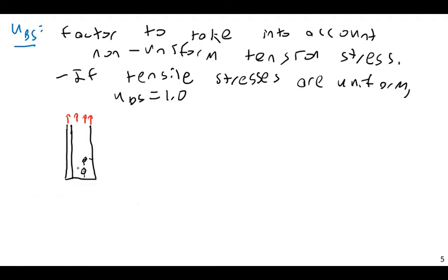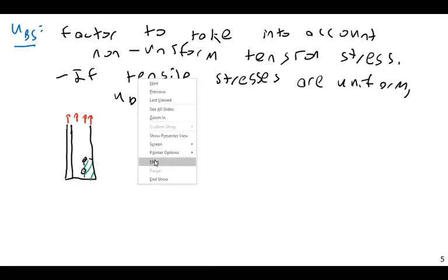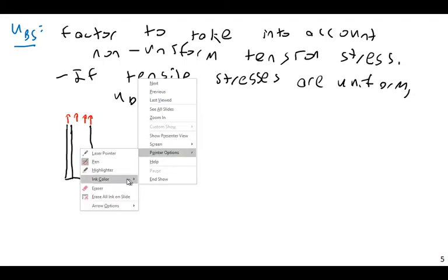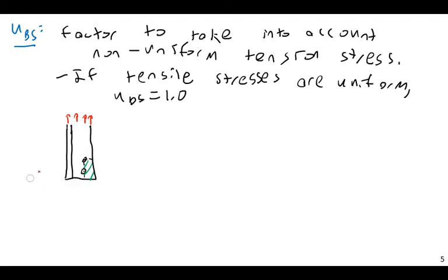This plane here will be in shear, and this plane here will be in tension. So this element is being torn out. We would have shear here, and we would have tension here. Now, the shear has its own capacity, but in terms of tension, all of this stress here has to somehow flow there.